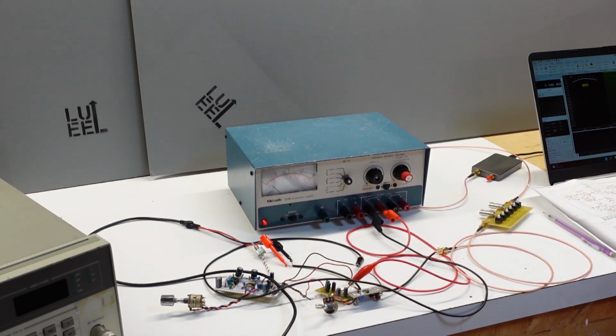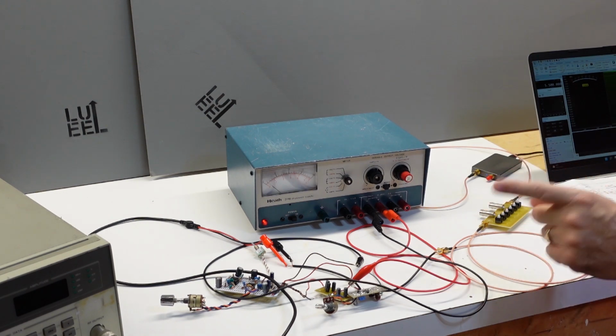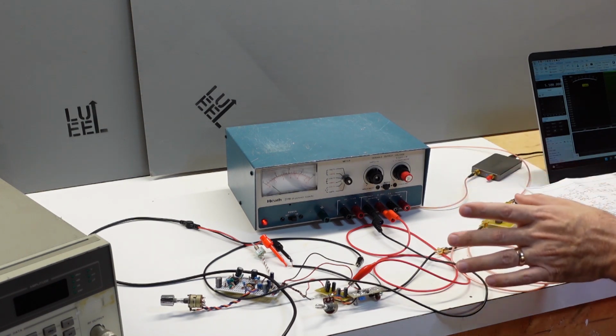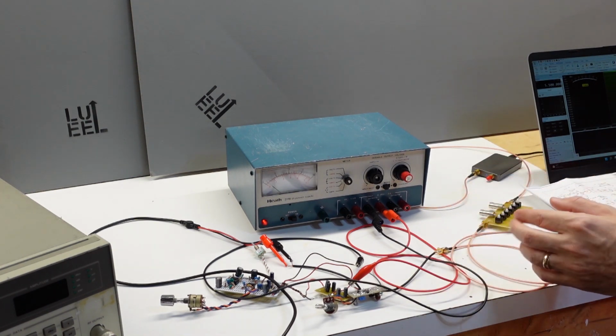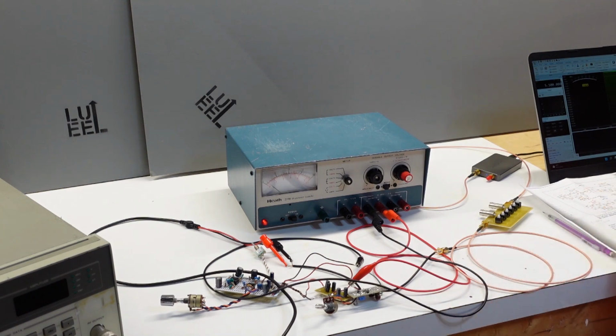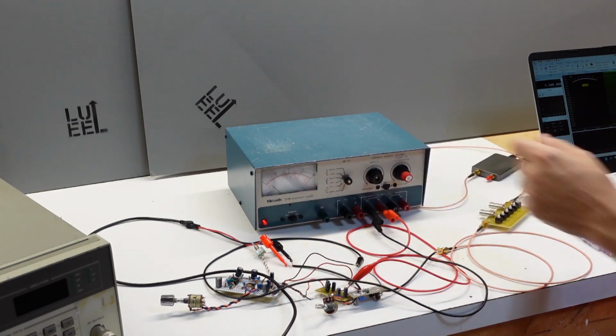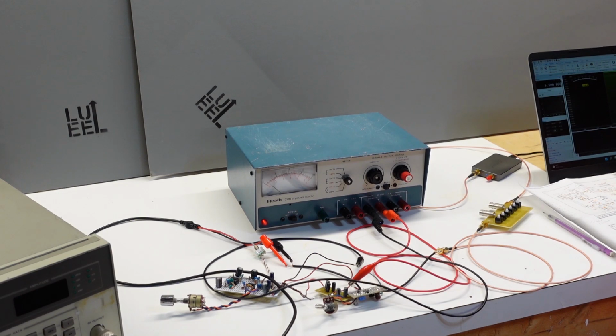And the key features of it are, it's got two tones. One you could switch on and off, and the two tones are not harmonically related to each other, so it's good to use this to drive a transmitter or other audio circuit where you're looking for intermodulation. The highest frequency tone, the way I got this built, is 1.89 kilohertz, and the low frequency tone that I can inject by switching on and off a little switch there is 803 hertz. It's a little bit off the design centers, but that's fine.